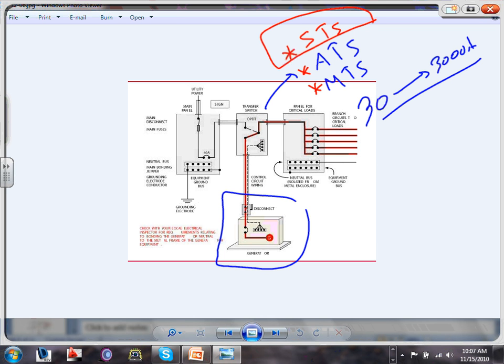With an auto transfer switch, you'll see the light go off, flip in the system, and come back. If you have a clock or something, you have to reset your clocks. My experience with them, Mr. Bew, is that an STS is for electronic equipment and other machines, because they don't want any downtime. They're very expensive. I just remember that they were so fast you couldn't tell. That's static transfer switches. They transfer electronically. I don't know how much they cost, but it's probably more than I'll ever see in my life.